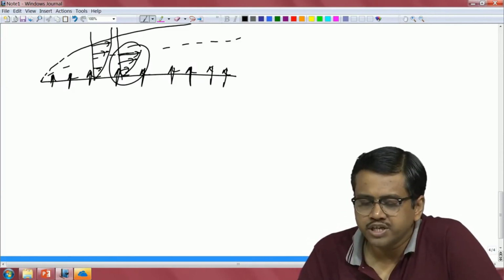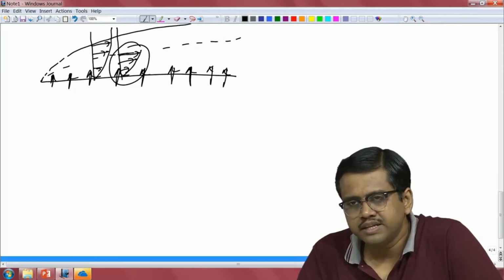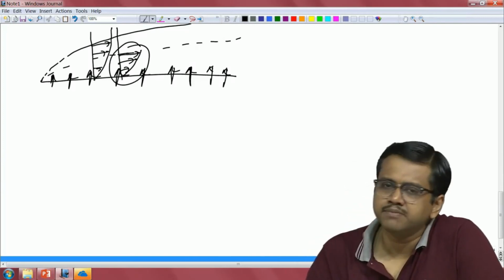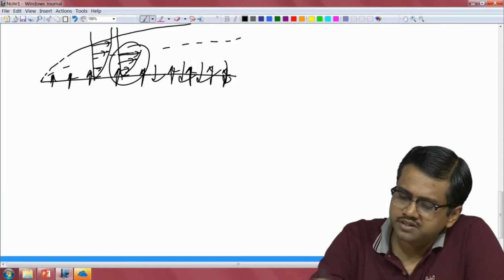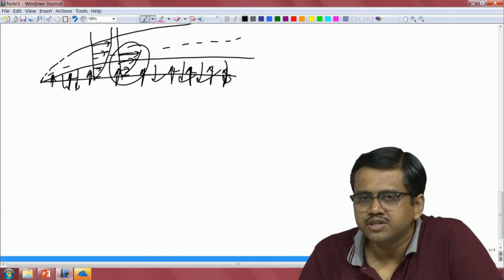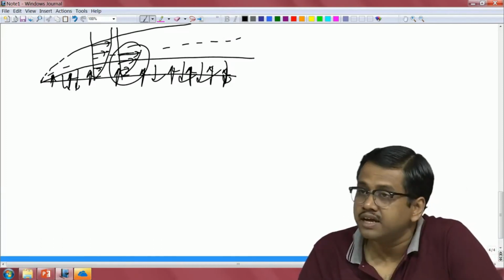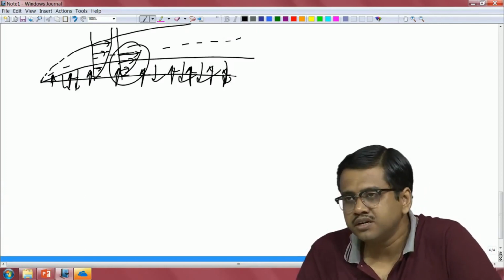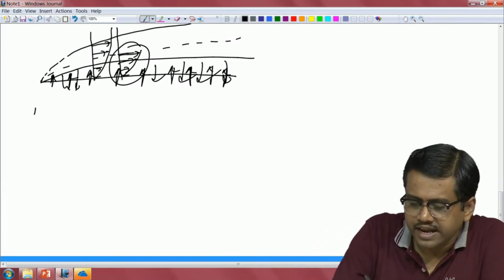If you talk about the same location, before blowing the boundary layer thickness was delta, after blowing it is, say, delta prime. So, obviously delta prime is more than delta. Similarly, when you have suction, that means when you have it in the opposite direction, the boundary layer becomes thinner. So, the gradients actually get enhanced. This proves why we are going to get a change in shear and obviously a change in boundary layer.